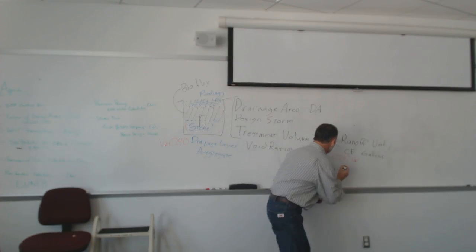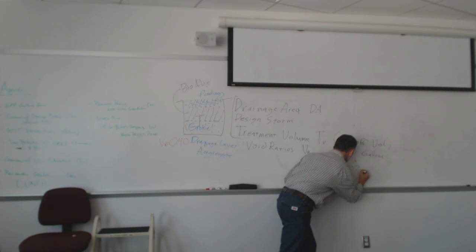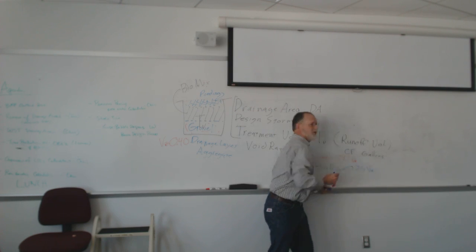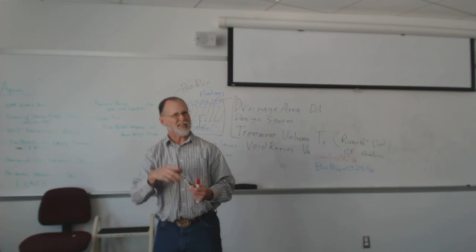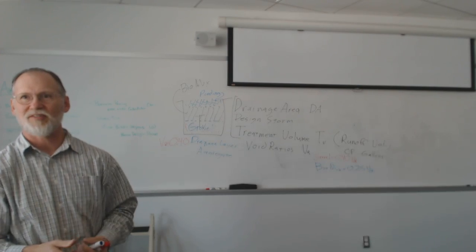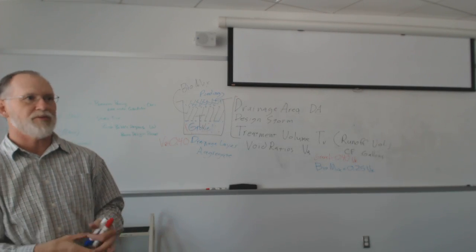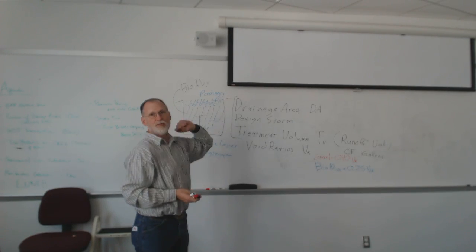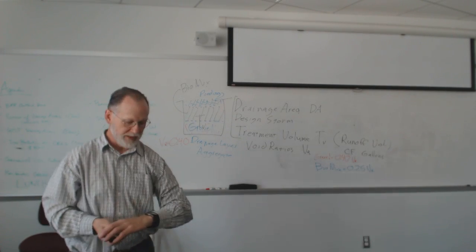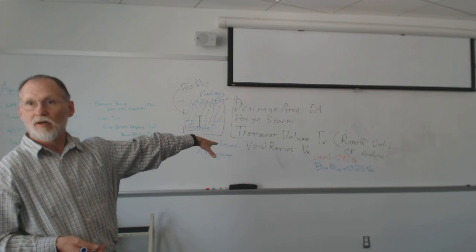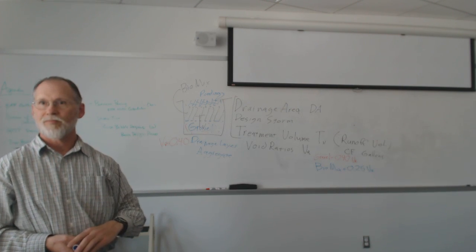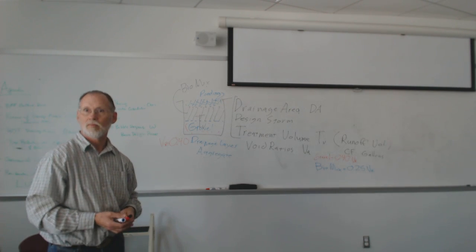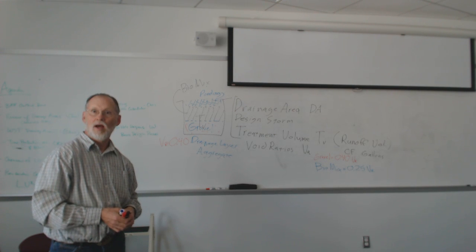So 0.25 is the void ratio for the biomix. It's kind of counterintuitive. It seems like there's hardly any room for water, but 25% of the volume that you've got for your rain garden mix, if you're using a BMP with rain garden mix, is going to be available for storing water. And is that because it's absorbing, and so you're actually cutting the pore space inside